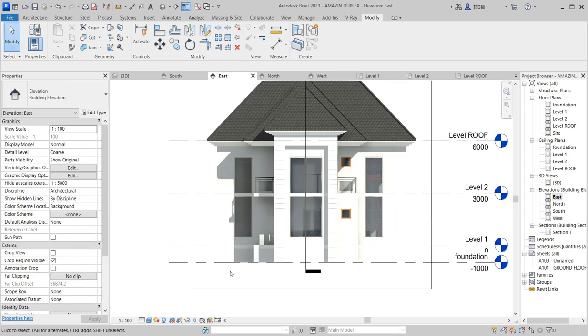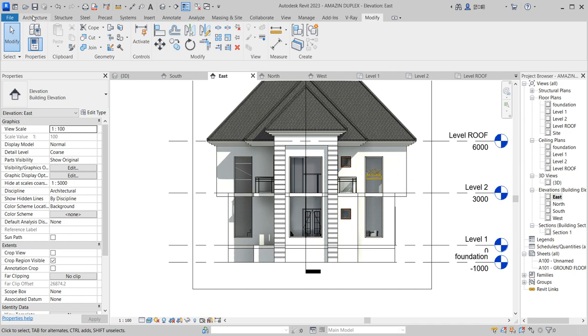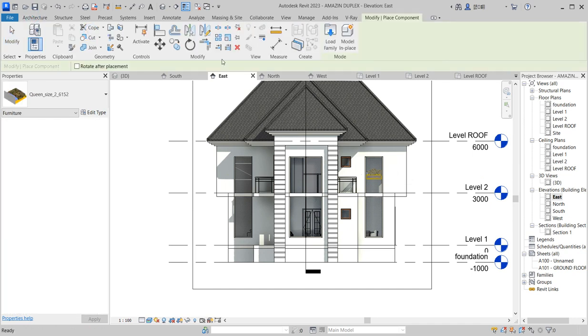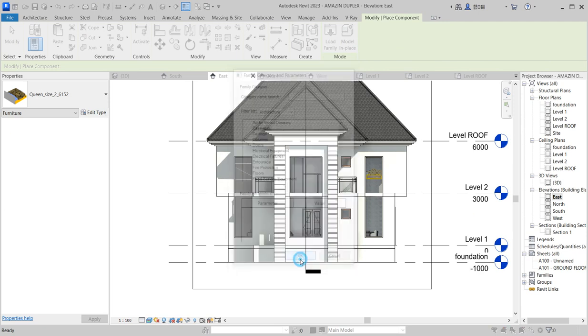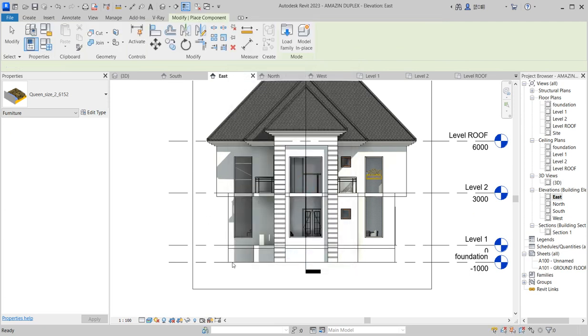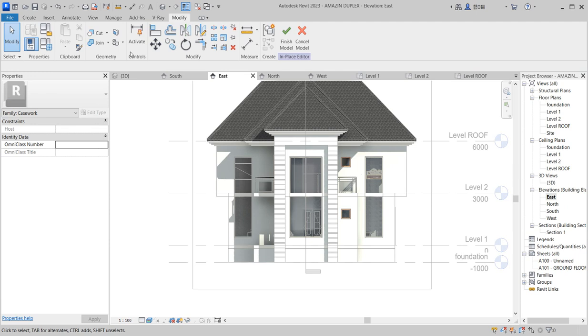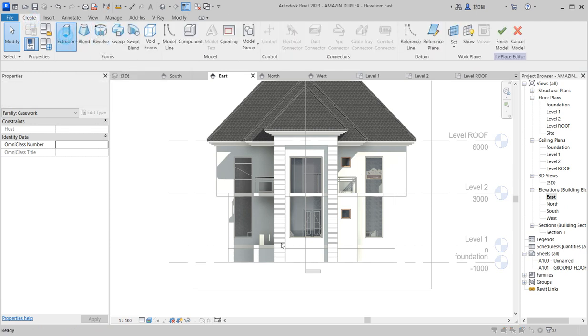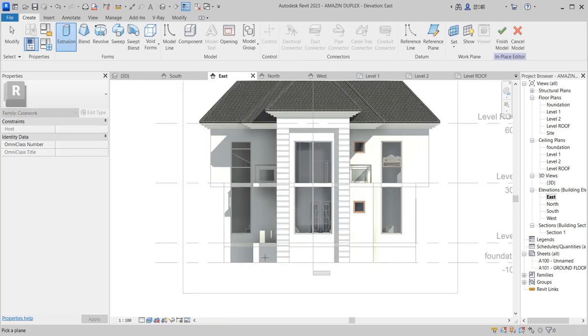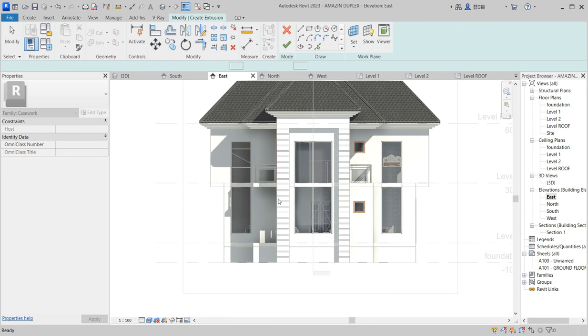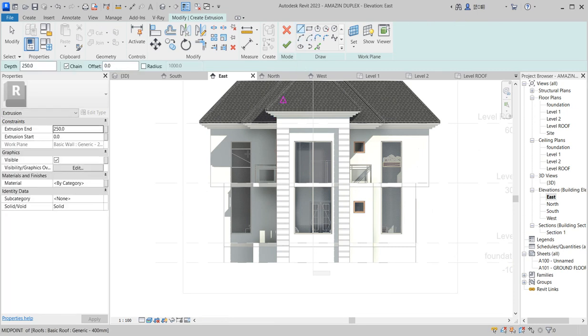that I'm going to use to enter into the house. So I'm going to go here and say component, put it in place and then use casements to do that. So click here and say casement. So I'm going to use this one. So I'm picking create. So I'm going to use extrusion. From extrusion I will just say okay. So I will use this as my guide.